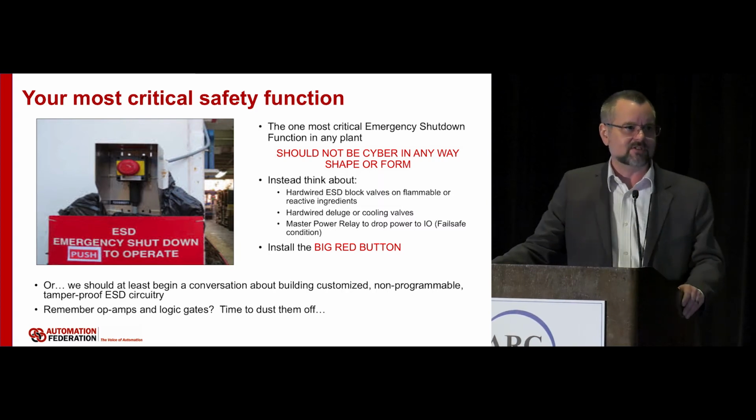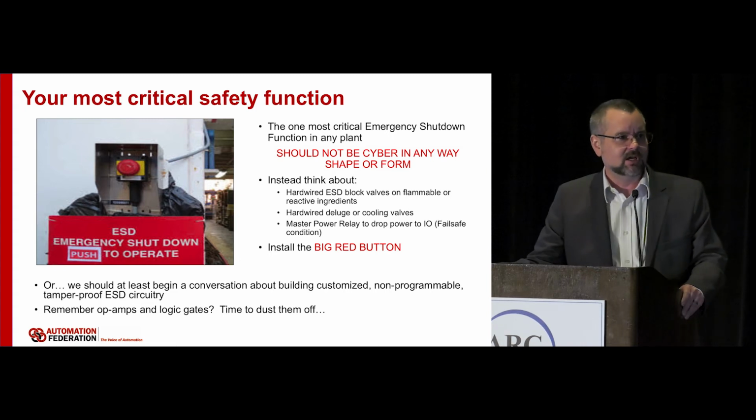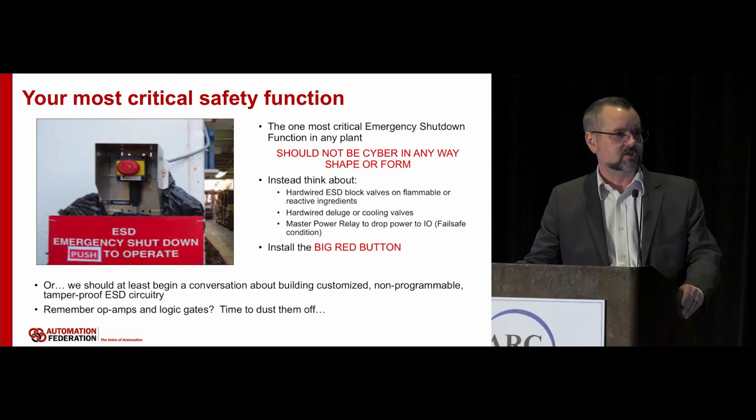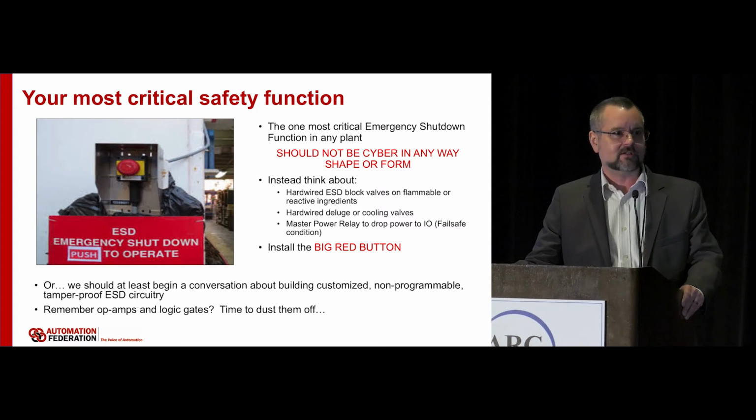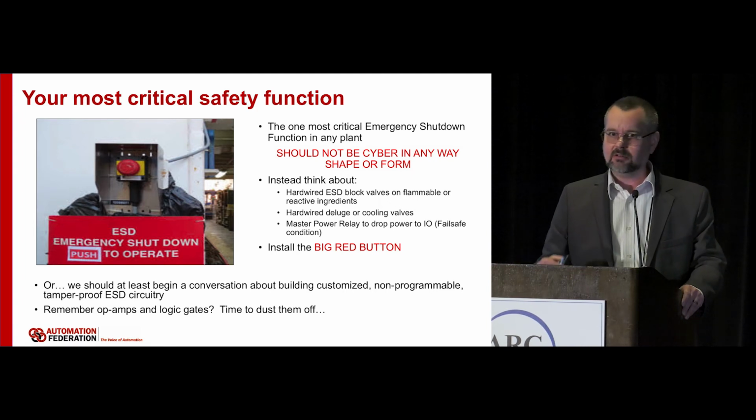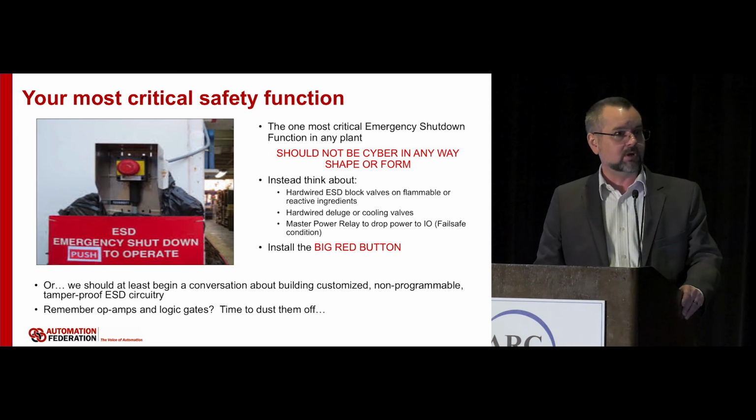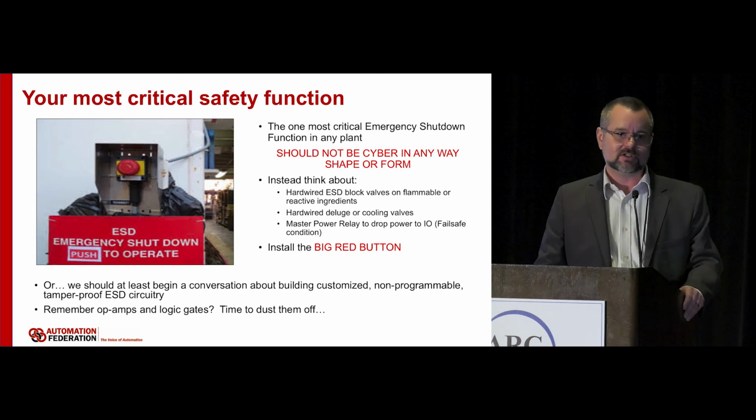Especially ask those questions of vendors that are promoting integrated safety and basic process control system platforms. Some are done extremely well, some not so well, right? And I think you need to ask the vendors the hard questions about how they implement this, how they manage the cybersecurity envelope around this, and more importantly, whether you are following their implementation instructions, right? So many times we see in the field that it's the way we've implemented these systems that violates the security integrity.